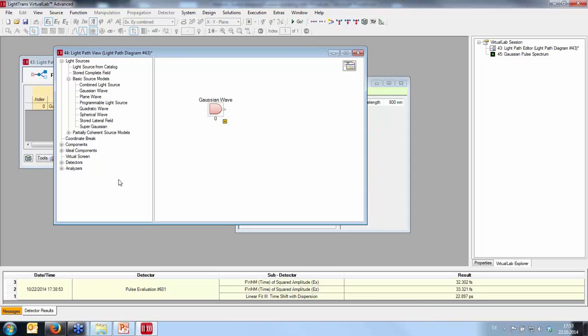On the other hand, I also could simulate a real grating, so I can really specify a very complicated stack of different grating interfaces, and some material in between. So I could really use the grating toolbox and do a rigorous Fourier modal method. It's a kind of Maxwell solver, and propagate the light through this.